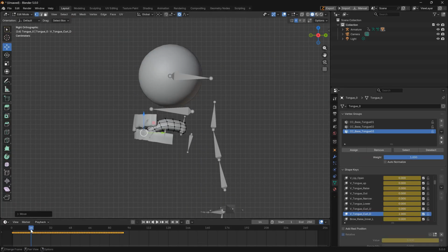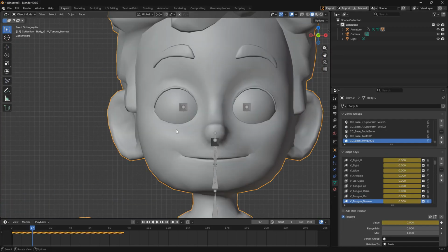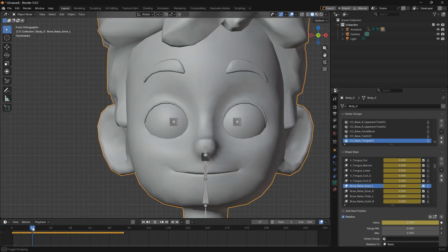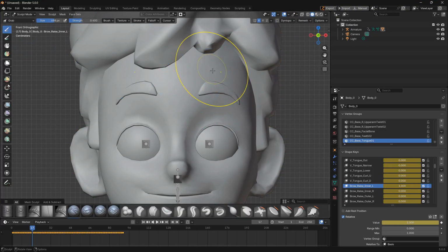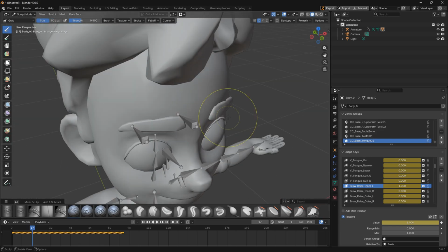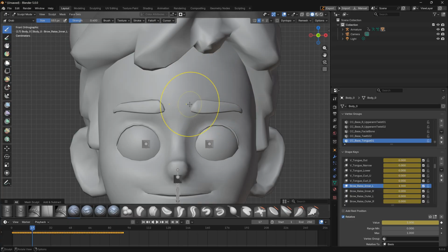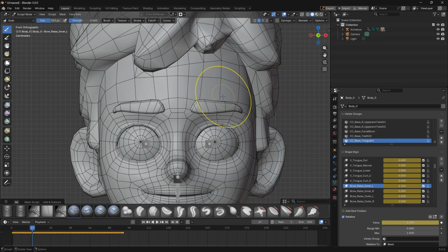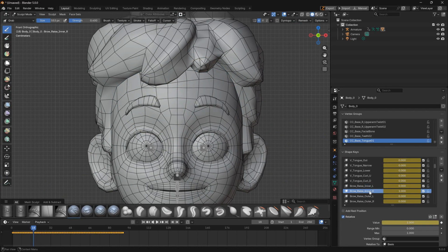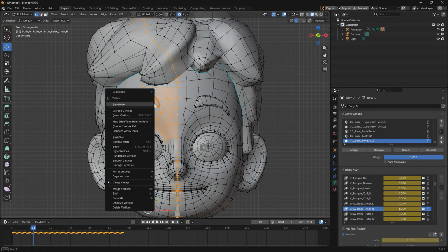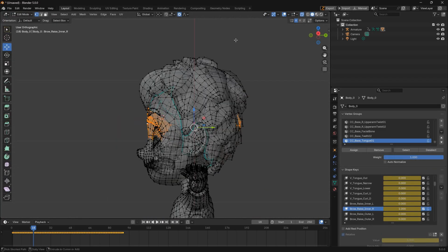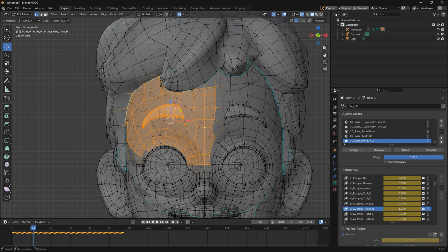Now, you may feel confident at this point that you have the process, but unfortunately you do not. The hardest part for a non-standard character is the fact that the shape keys are divided into right and left, and sometimes right, left, up, and down. So you have to be a bit clever in editing them. If your character is very non-symmetrical, that can actually be a bonus, because you won't have to make the expressions even on either side.